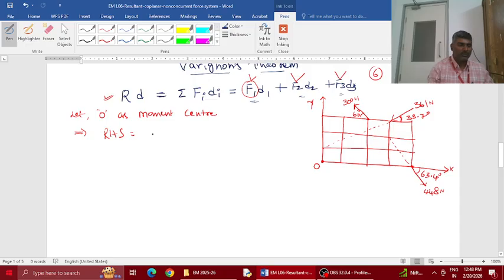So it is this 448 force. The X component is passing through this point, so I'll have only the Y component moment, which means 448 sine 63.4 degrees is the Y component, into the distance between this point and this Y component, which is 4 meters. And the direction is clockwise, so I take clockwise as positive.